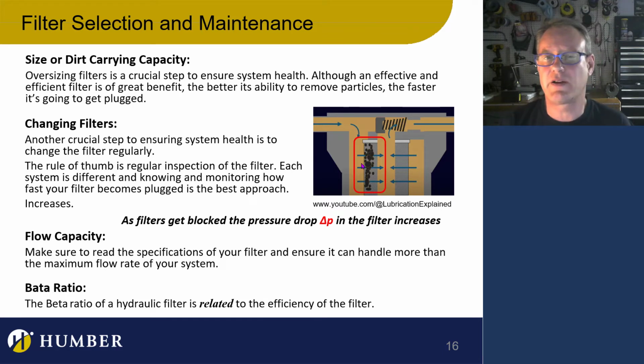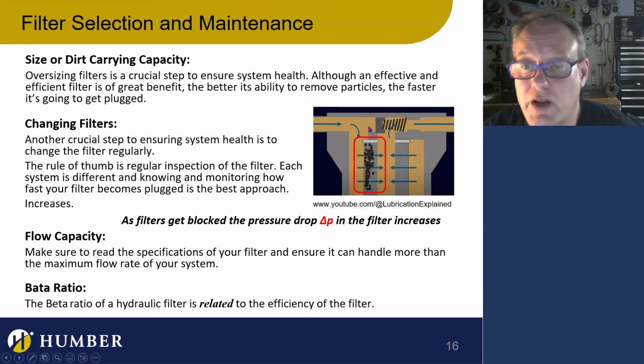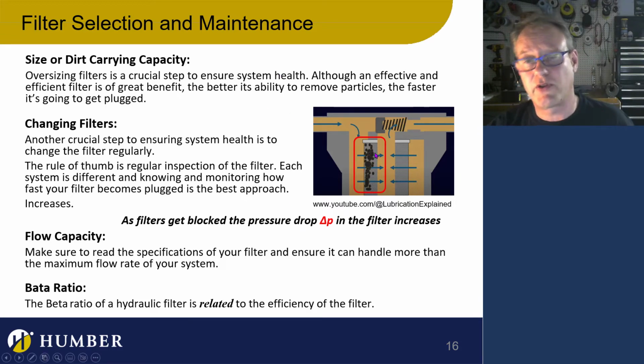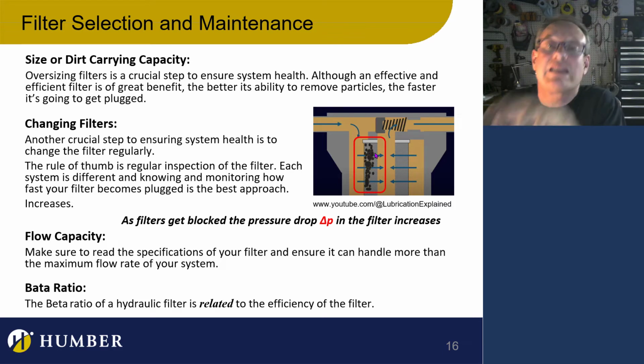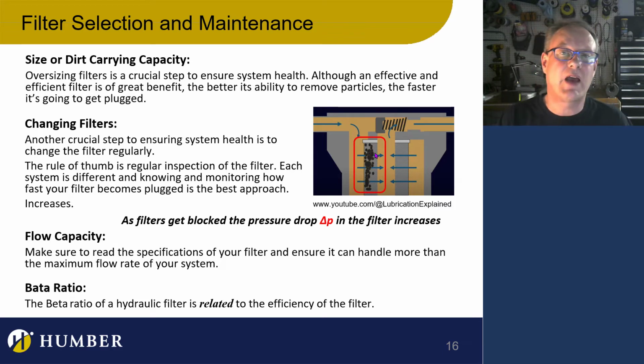But my point here is that if it gets dirty, there's a greater and greater pressure loss to the point where it's so bad that a check valve is going to open up and the fluid is just going to flow through. So dirt carrying capacity of a filter is just the size of the filter. So you want to oversize it so that it can collect dirt, because it's going to. That's its purpose and function. You want it to collect dirt.